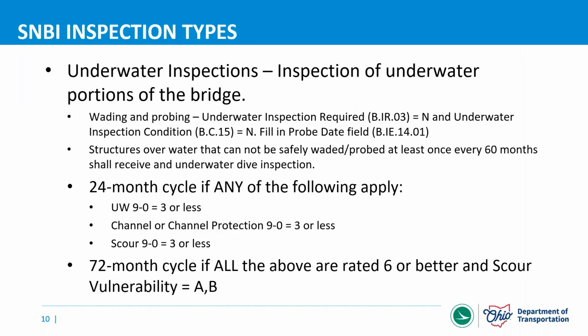We can get out there and do a probing inspection. Then that can replace that underwater inspection date, and you can reset that interval for another 60 or 72 months.